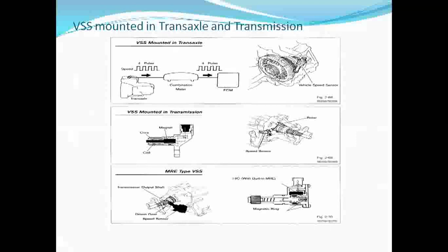So depending upon the acceleration process, simultaneously this camshaft timing chain needs to be changed by the programming given by this particular processor, and that processor will be guided from the controller. So depending upon the feedback from this particular sensor, simultaneously the guidance will be given to the processor from the controller to increase the speed or decrease the speed.